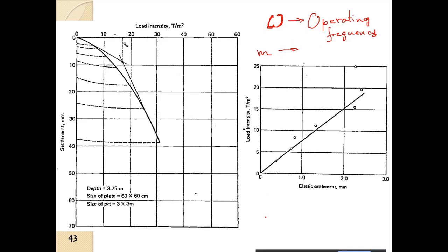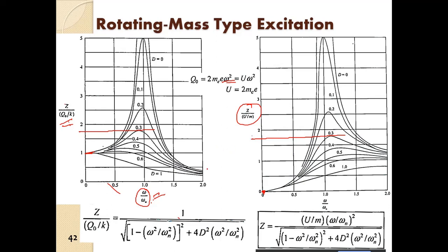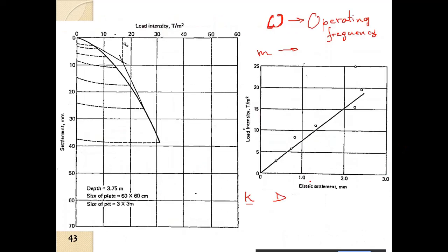What we have to determine is the spring constant, and if there is any damping, the damping. Of course, since we are considering higher variations in the frequency of operation and the natural frequency, the damping is not very effective, so it is considered that there is no damping; damping is neglected, right?